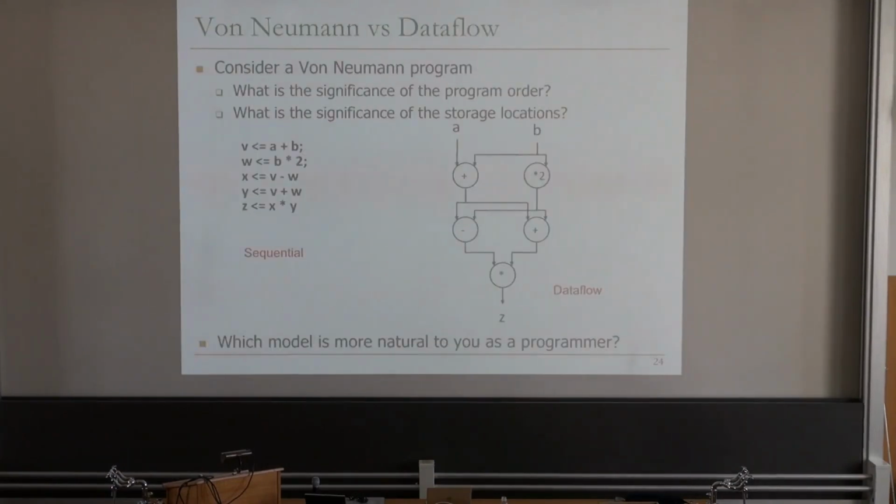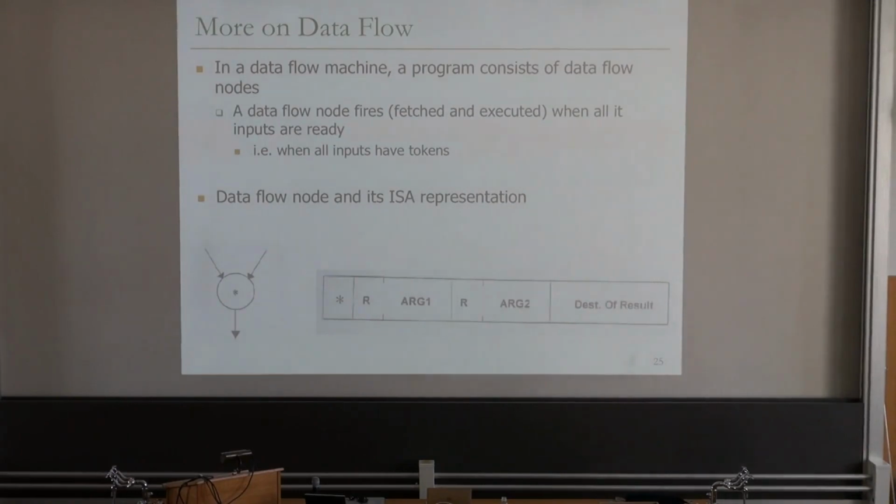With an FPGA, it's completely different. You don't really need to turn this into an instruction, right? With an FPGA, you just go and somehow make sure the connections are switched correctly such that this node gets connected to this other node, and then you instantiate an adder over here and then ensure the flow of data. Of course, if your data flow graph is much bigger than your FPGA, you have a problem, right? Or if you have constraints in your FPGA, then it becomes a problem. So you need to handle all of these real-world ugly cases, and the real world is not that nice. Okay, but this is the data if you want to turn it into an ISA.